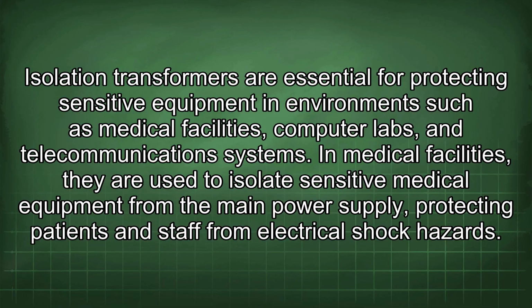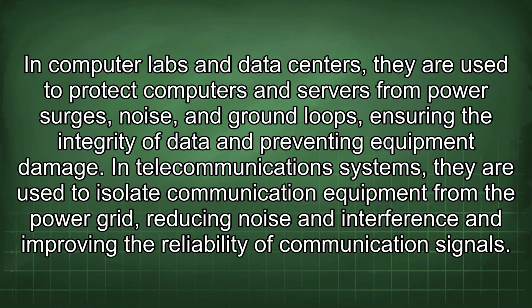Isolation transformers are essential for protecting sensitive equipment in environments such as medical facilities, computer labs, and telecommunications systems. In medical facilities, they are used to isolate sensitive medical equipment from the main power supply, protecting patients and staff from electrical shock hazard. In computer labs and data centers, they are used to protect computers and servers from power surges, noise, and ground loops, ensuring the integrity of data and preventing equipment damage.